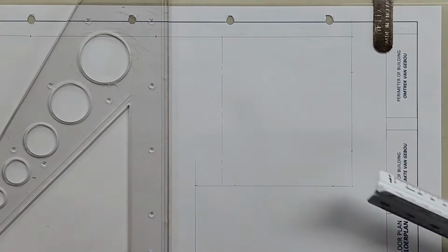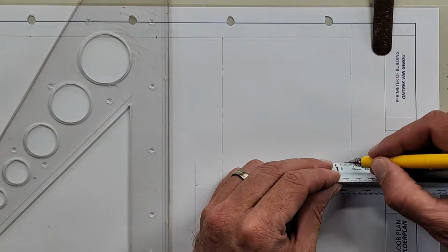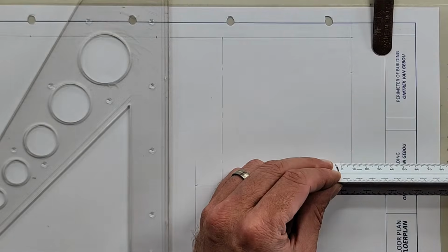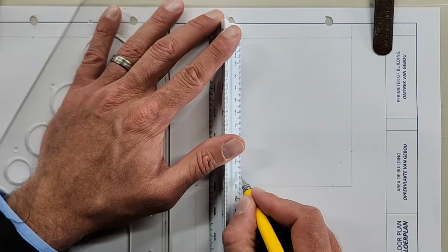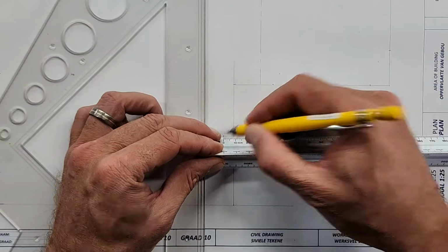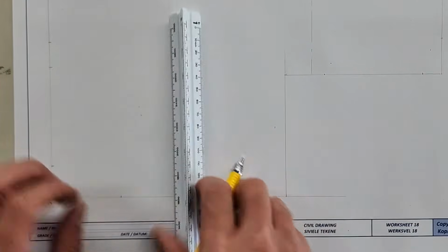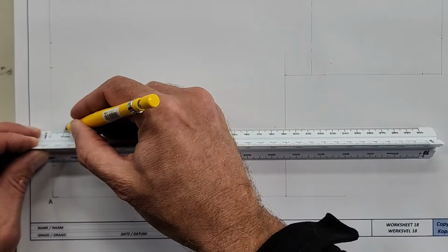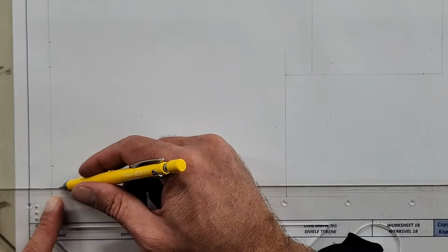All right. Then all these walls, the external walls is 220, which comes down to 8.8 millimeters. So that's about 9 millimeters. I'm just going to make a mark here on all of them. It's just the external walls. Do that quickly, all the way around. Indicate that 9. Alright, and then in construction, I can draw them in quickly. Do the horizontal lines.